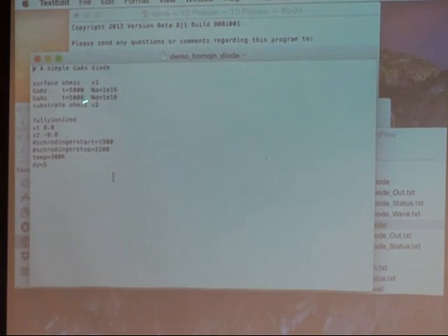Then I have 1E16 doping, 5,000 angstroms. It takes units in angstroms. Then 500 nanometers, or 5,000 angstroms, of p-type doping, Na, 1E16. And then you have a surface. Very simple PN diode, right?